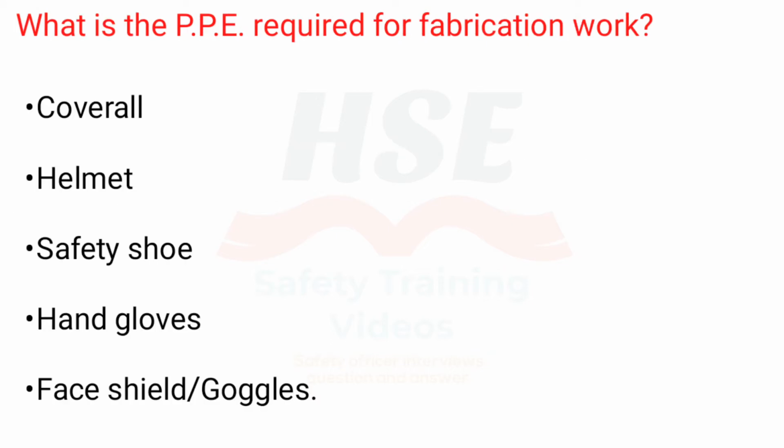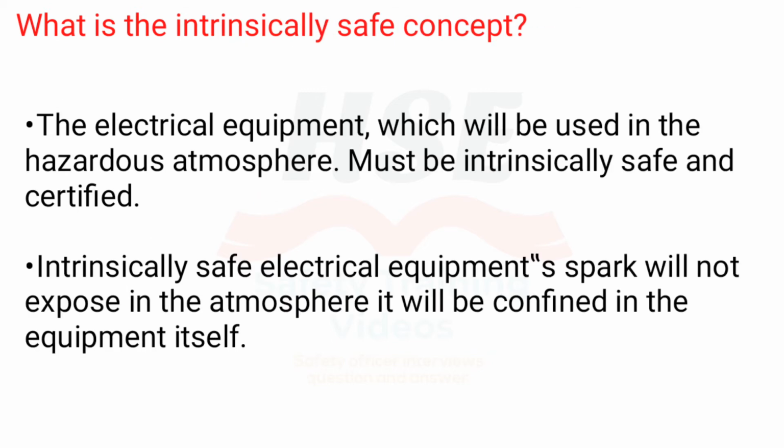What is the PPE required for fabrication work? Coverall, helmet, safety shoe, hand gloves, face shield, goggles. What is the intrinsically safe concept? The electrical equipment which will be used in the hazardous atmosphere must be intrinsically safe and certified. Intrinsically safe electrical equipment's spark will not be exposed to the atmosphere. It will be confined in the equipment itself.